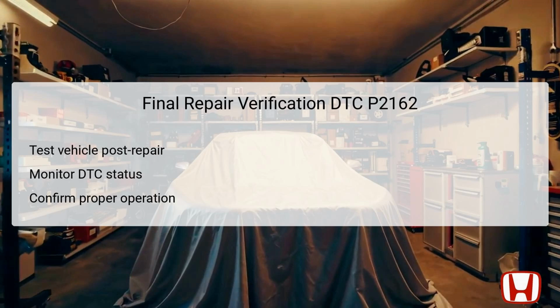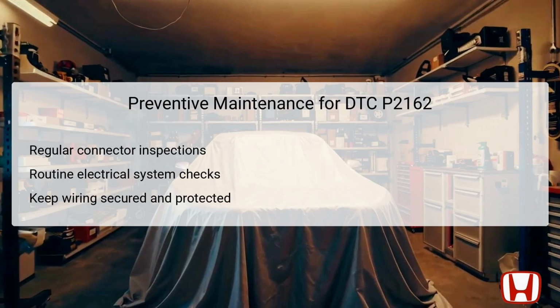Preventive maintenance can help avoid DTC P2162 from recurring in the future. Regular inspections of connectors and wiring associated with the vehicle's speed sensor and TCM are essential. Look for corrosion, wear, or any loose connections that may arise over time.